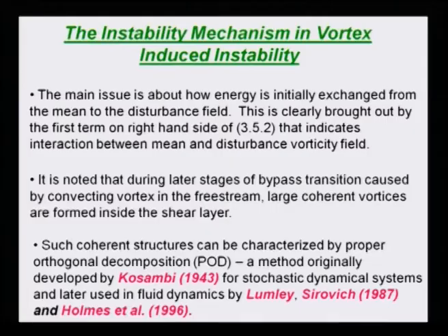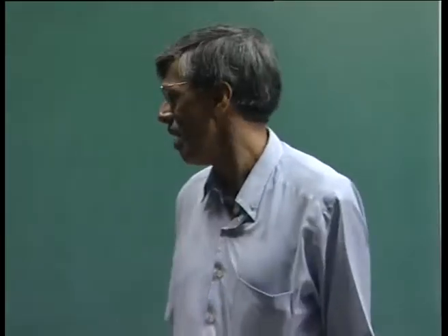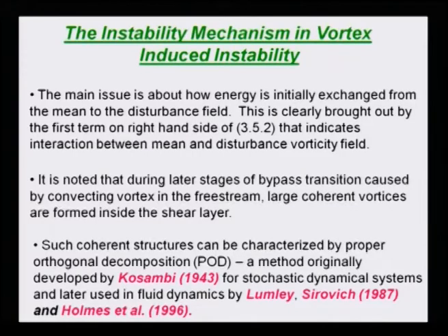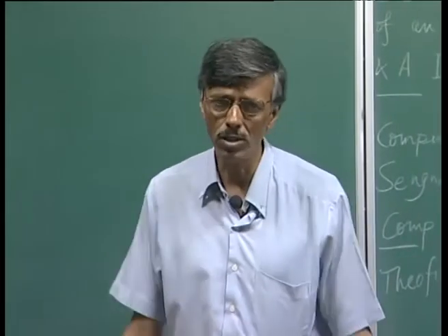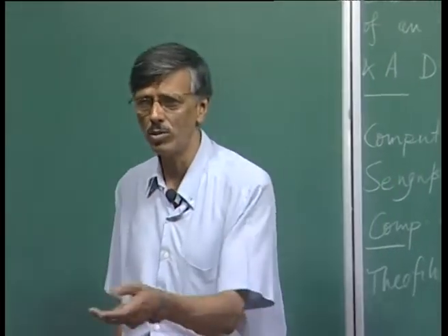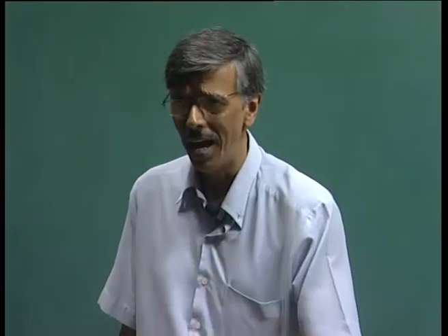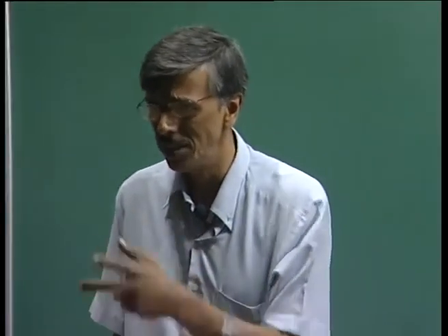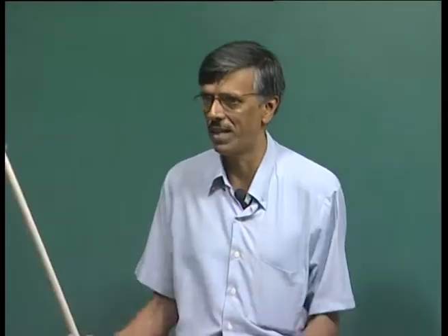So, if you are looking at a truly continuum system, you will have a very large number of them. But then Kosambi suggested that you look at such a system, but focus upon the energy content of each of these modes, and you decide that you want to describe, let us say, the first 80% of the energy or the first 99% of the energy, and then you would see this number of modes required to describe that quantum of energy is not necessarily infinite, they are finite in number.